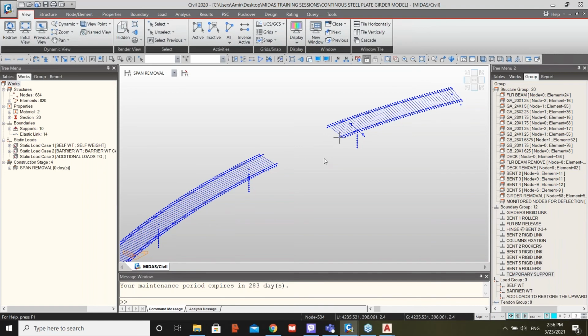The main aspect I'm talking about is this upward deflection at those particular points, because later on when you get the new girder and install it on this bridge, you want to make sure the tips of the two girders are on the same level. Otherwise, it's going to be impossible to install or erect it. So you need to have full control of the deflection at those ends, here and here.